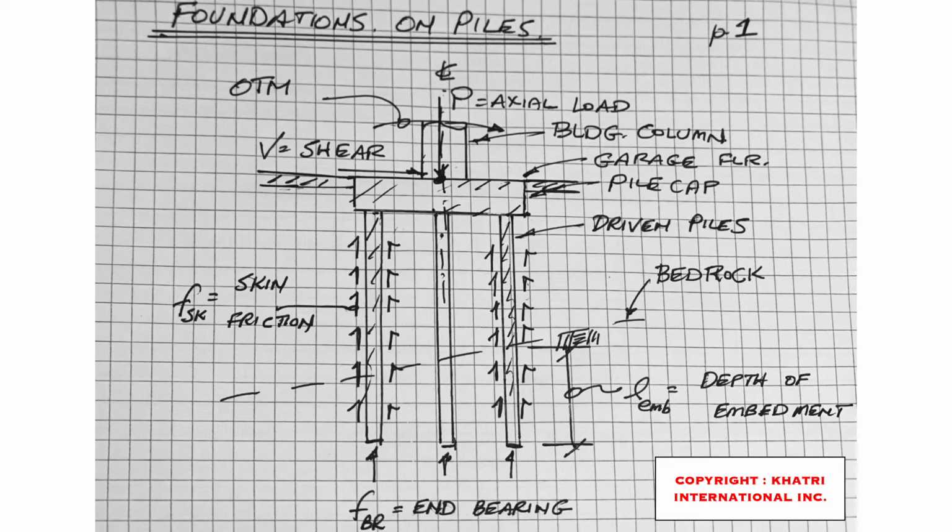We have a terrible example of this occurring in San Francisco right now with the Millennium Tower that is sinking and tilting. And it's exactly the same situation as this diagram, except that in my diagram here, the piles went into bedrock. In the Millennium Tower, the piles did not go to bedrock. And that is probably a much more complicated situation, but the principle is the same: as the building continues to sink, it has a dramatic, detrimental impact on the structure above.